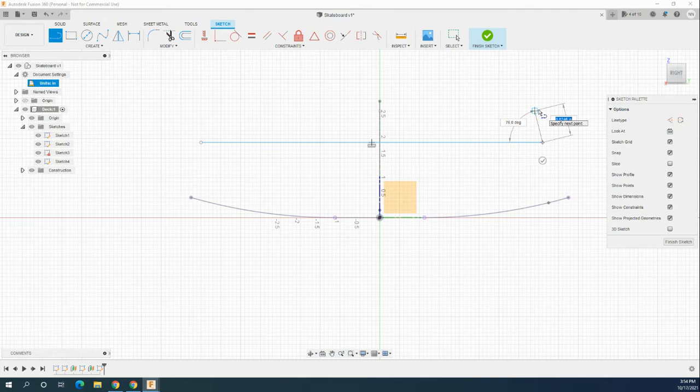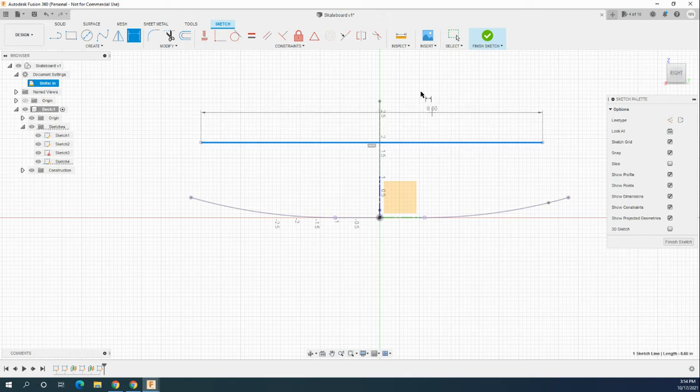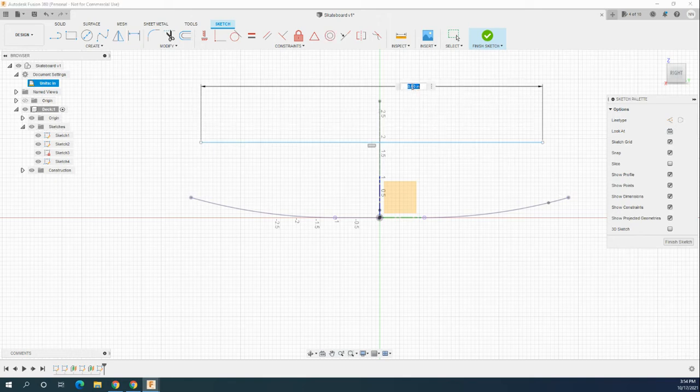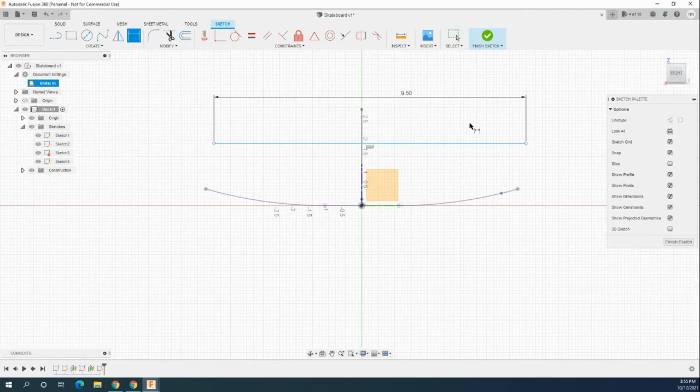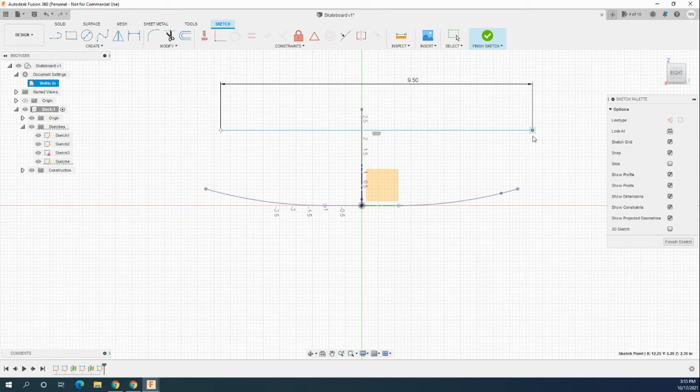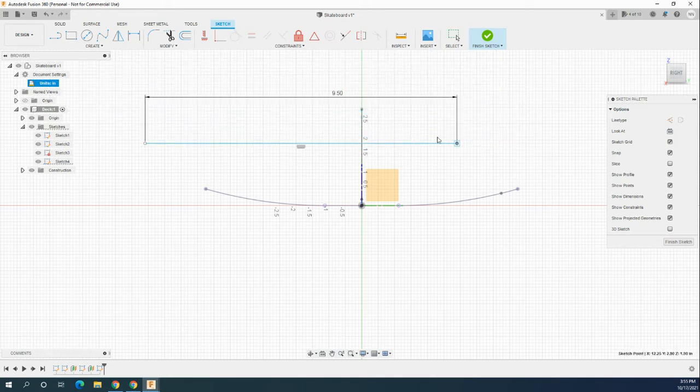Well, it's okay. I'm going to dimension it. I'm going to hit Escape, I should have double clicked. I'm going to hit D to dimension it. Click and let go of that. Click to set that down to 9.5 inches, 9.5, enter. And then this thing is horizontal, right? It can't rotate, but it doesn't know where it lives.